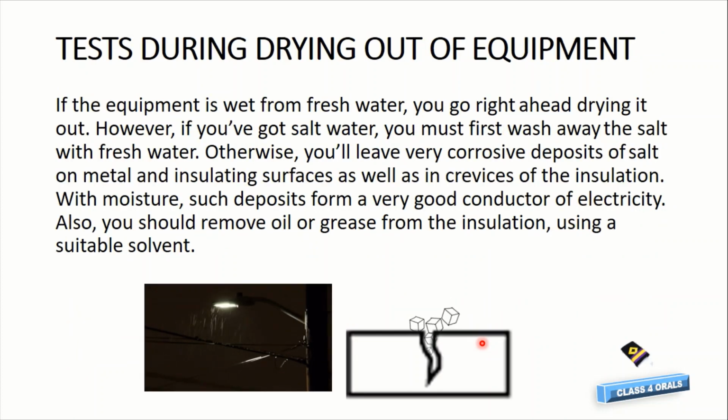Now, before going for the testing of IR, suppose the equipment is wet from fresh water, then you have to make it dry. And suppose you have sea water or salt water, then you must first wash away the salt with fresh water. Otherwise, you may cause corrosive deposits of salt on the metal and insulation surfaces.